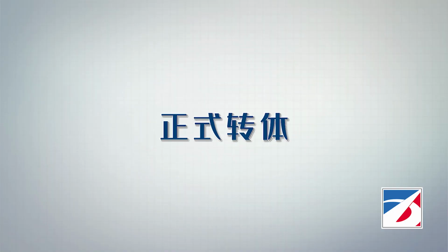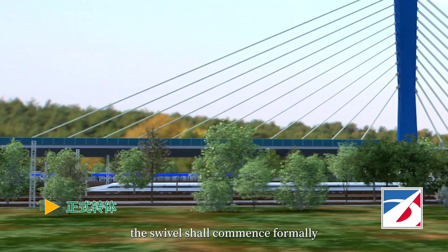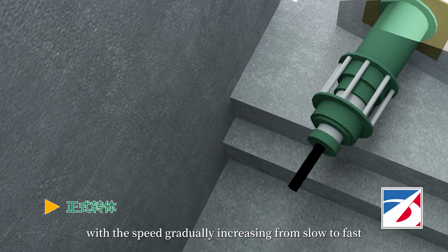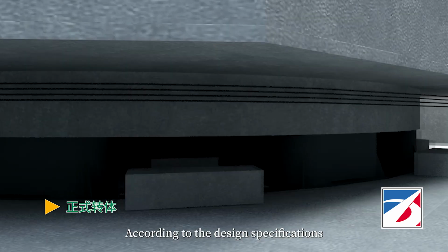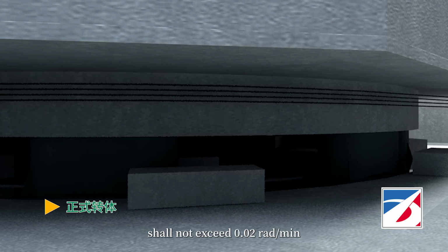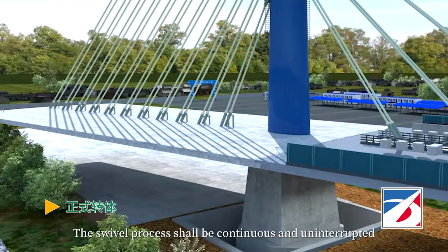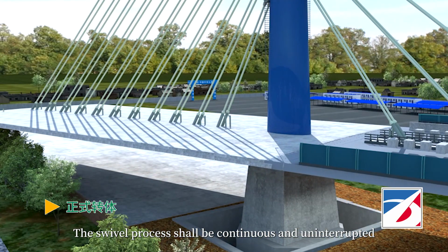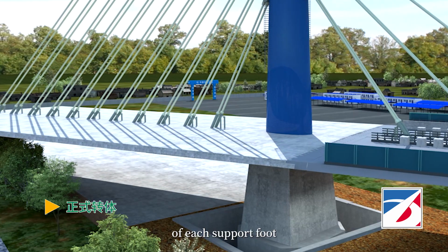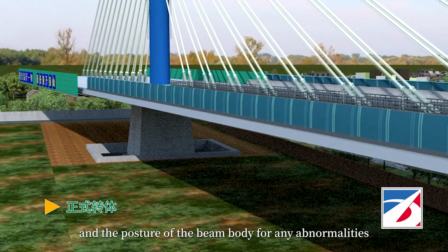3. Formal swivel. Upon receiving the swivel command, the swivel shall commence formally, with the speed gradually increasing from slow to fast. According to the design specifications, the maximum swivel angular velocity shall not exceed 0.02 rad per minute. The swivel process shall be continuous and uninterrupted, with close monitoring of the sliding conditions of each support foot and the posture of the beam body for any abnormalities.